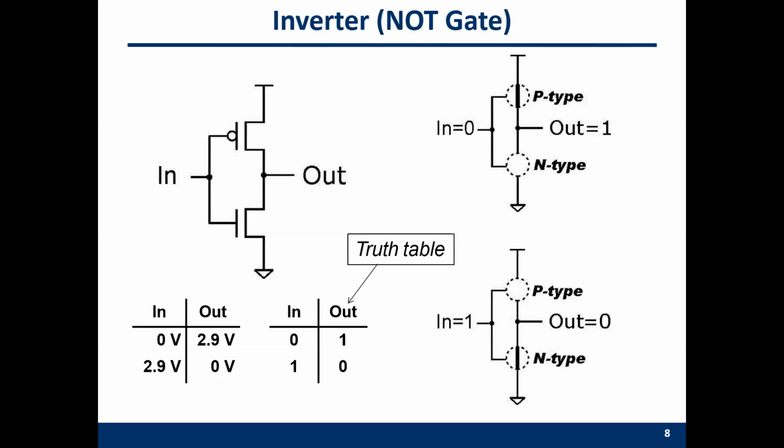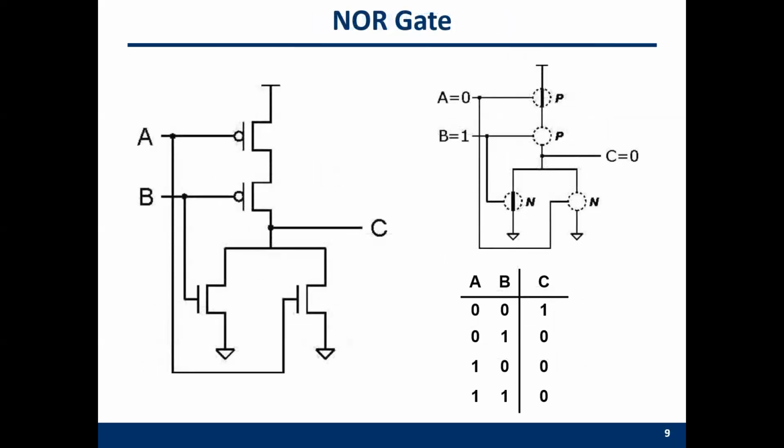And then the VDD can pass through this gate and to here. Then your output is 1. So this is why we have a 0 here, 1 here. Any question? So by simple 2 gates, simple 2 CMOS transistors, we can actually build an inverter. This is a NOT gate.